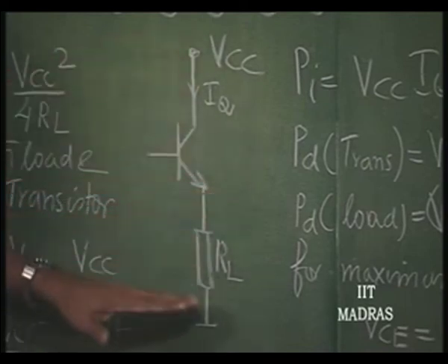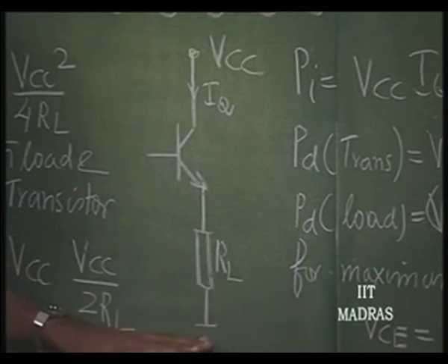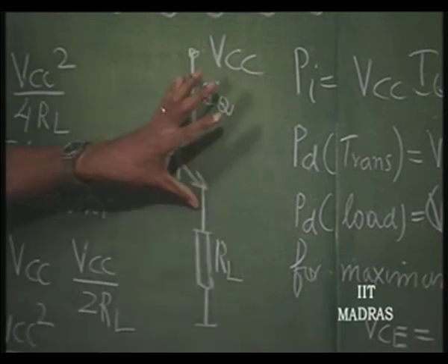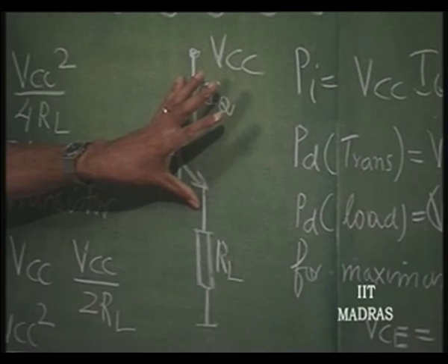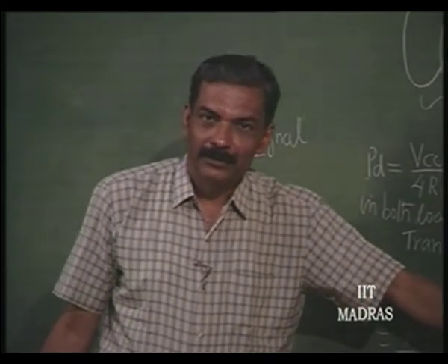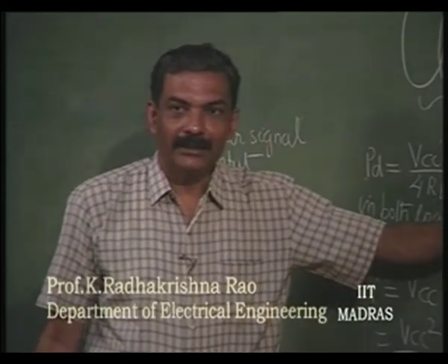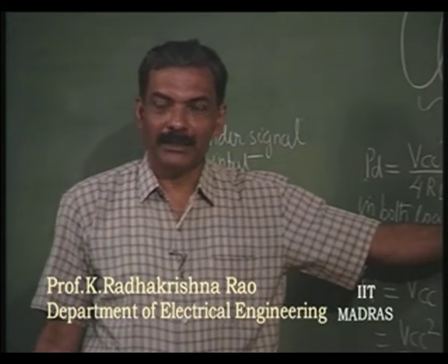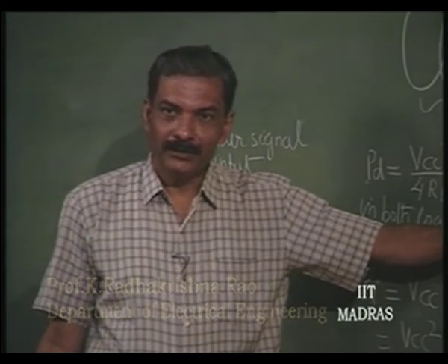Earlier 50 watts was getting dissipated here, and that 50 watts continues to be dissipated, then the transistor is going to dissipate a further DC power of 25 watts. This 25 watts, which was earlier getting dissipated as DC power, is getting converted into AC power. So, that is why this active device is responsible for converting the DC power into AC power.